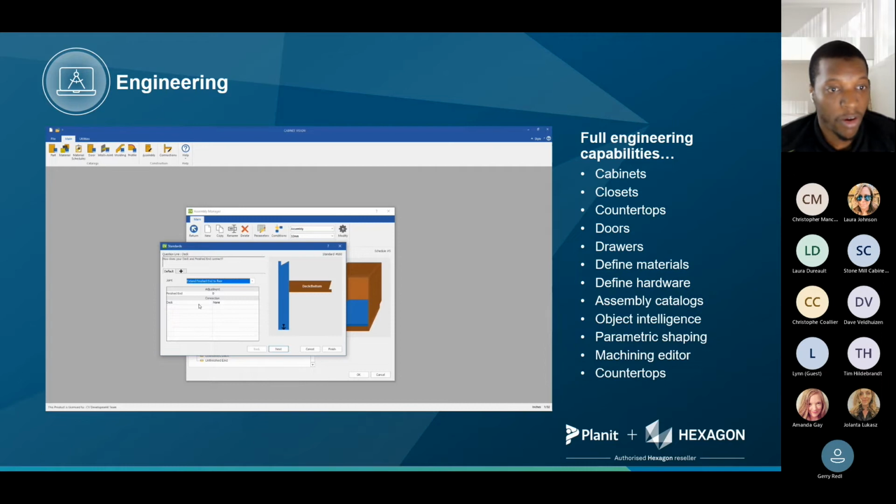And then over the years, you can keep adding more and more rules, update them down the road as well if you want. And in every single job, you can still override those specific parameters. So if you say you want a cabinet construction where your toe kicks are by default 4 inches, you can easily go on one cabinet and update the toe kick height to be 6 inches or 4.5, for example. You can even do it by room.